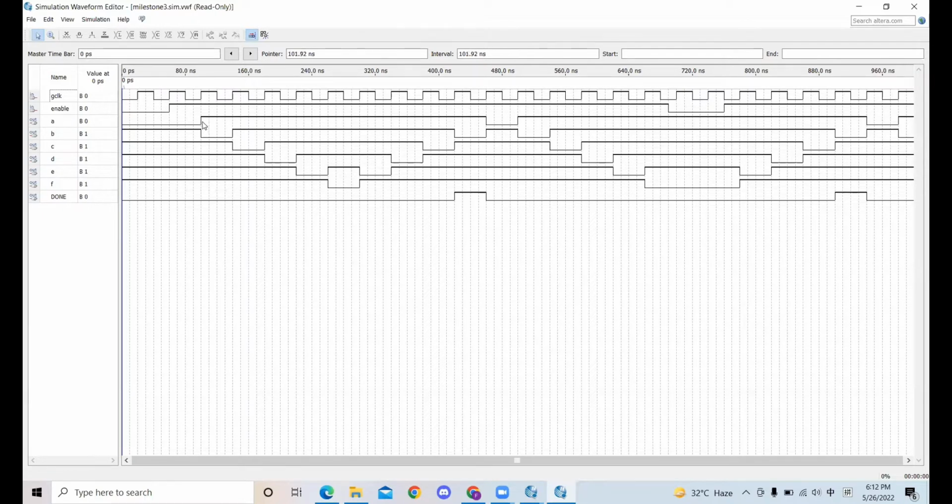As you can see, every time the circuit approaches the rising edge of the clock and the LEDs start to show the Knight Rider pattern, the unlit LED changes from LED A to LED F and then returns to LED B. After that, when a cycle is completed, output high is sent to the done LED to indicate the completion of a cycle. And this depicts the success of our Knight Rider design.